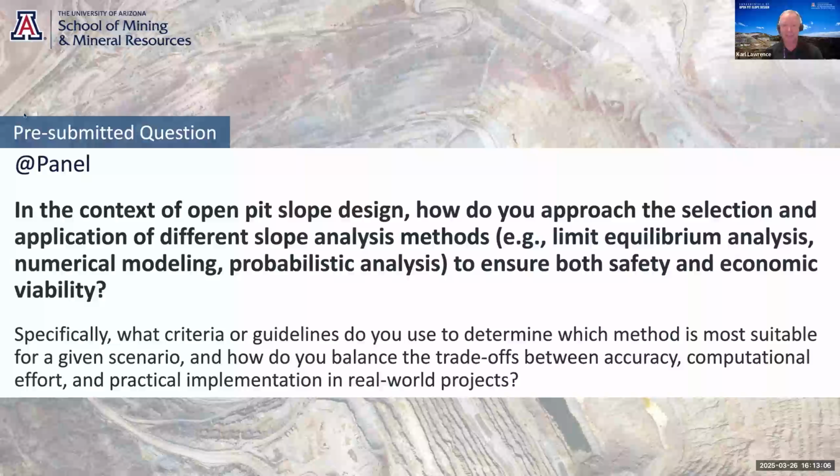And I think it really comes down to what's driving the slope design. Is it bench scale kinematics? It doesn't make sense to run an overall scale, big 3D numerical model if your only challenge is rockfall and bench design. So it comes down to what's driving the underlying mechanisms and what's driving the design in terms of choosing between these.